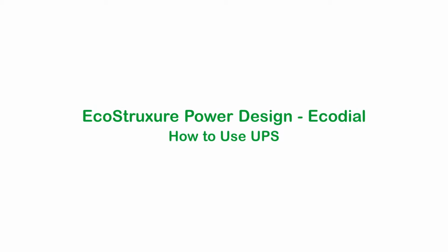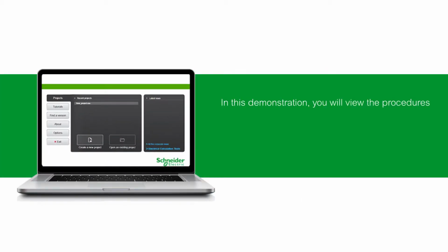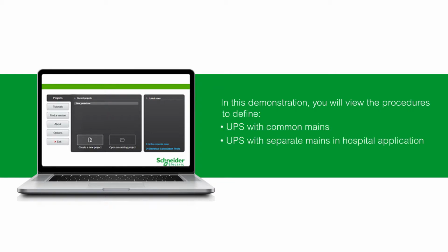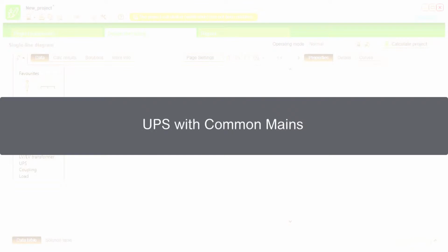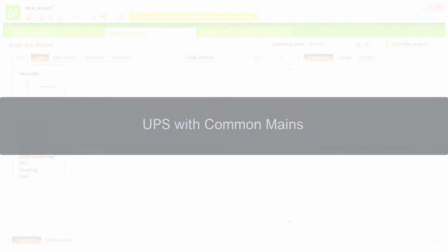Hello and welcome to the video tutorial on how to use UPS in EcoStruxure Power Design Ecodial. In this demonstration, you will view the procedures to define UPS with common mains and UPS with separate mains in a hospital application, for example.